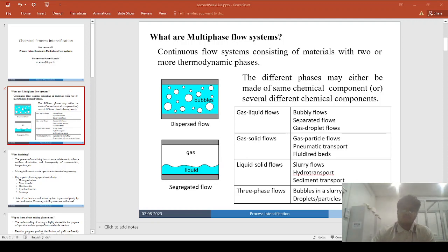Now coming to the liquid-solid systems, here the solid particles are dispersed in liquid. Similar to the gas-solid system where the solids are suspended in the continuous gaseous phase, here the solids are suspended in the liquid phase. The solid particles act as the dispersed phase. Some examples of the liquid-solid system involve the hydraulic conveying of solid materials, and slurry flows over a wide spectrum of applications that range from the transport of coals and ores to the flow of mud.